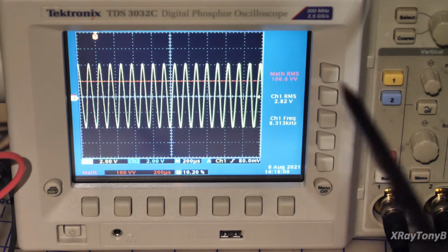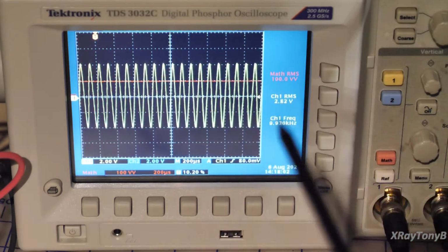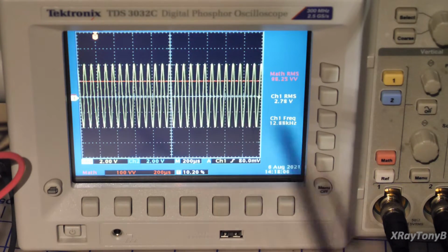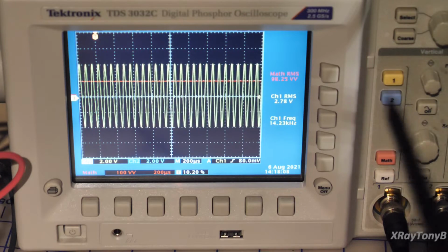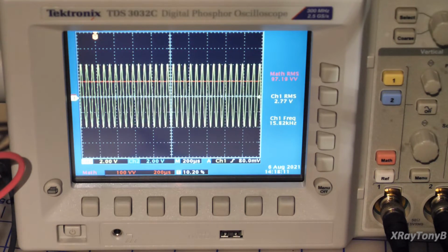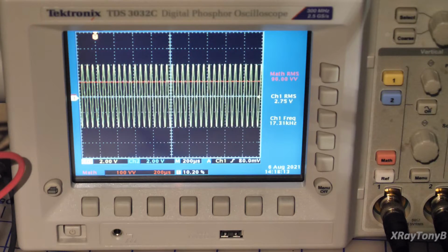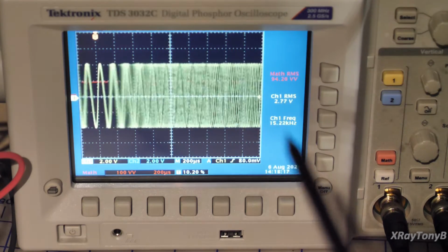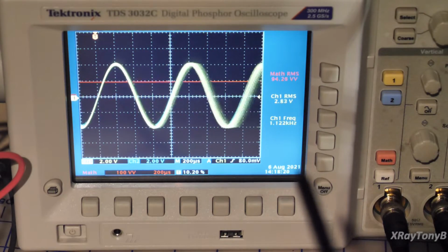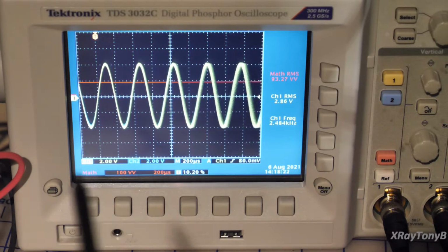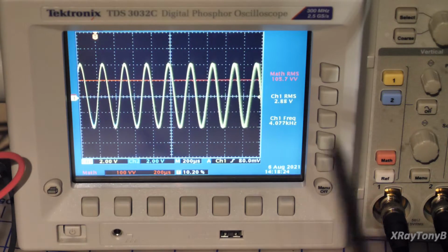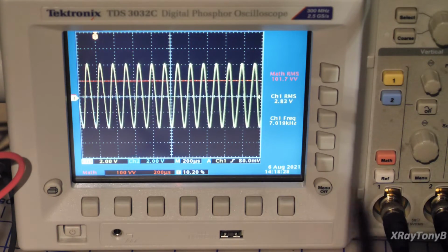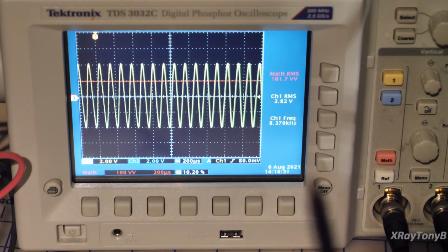But what you cannot see with this is how it is shifting the phase at the speakers with respect to the input terminals of the amplifier. And of course, if you have phase shift at different frequencies like that, at a single frequency it doesn't matter, but if you're listening to a complex waveform like music and it's shifting the phase of the bass notes with respect to the mid-range, that could theoretically cause a little bit of distortion.